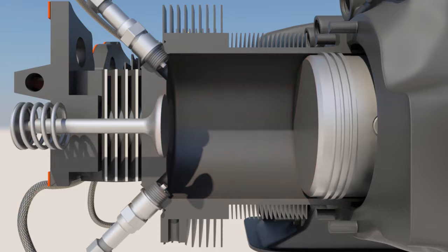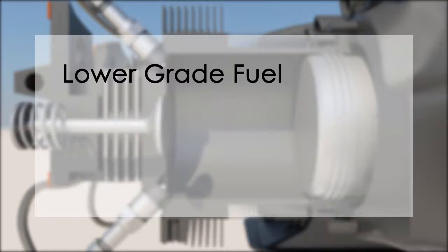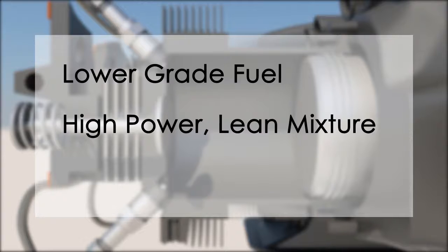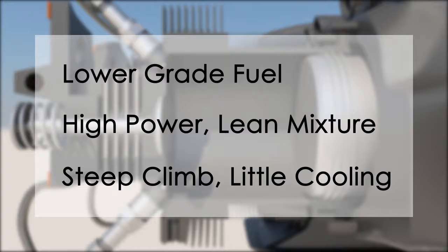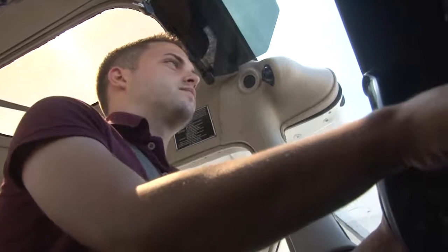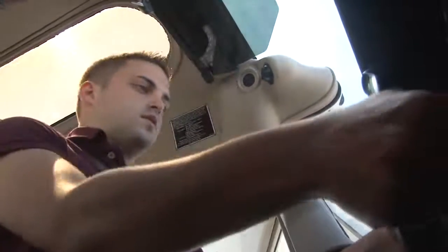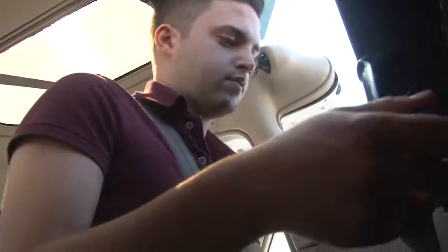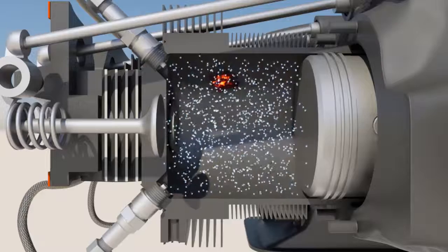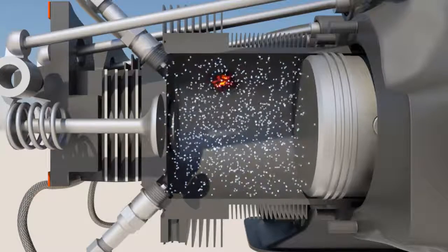Detonation can happen for a variety of reasons, including using a lower grade fuel than what is recommended, high power settings with the mixture set too lean, or climbing too steeply with cylinder heads not cooling appropriately. If detonation is occurring, the pilot should reduce the power and increase the mixture, which will allow for better cylinder cooling. Another issue that can develop is pre-ignition.